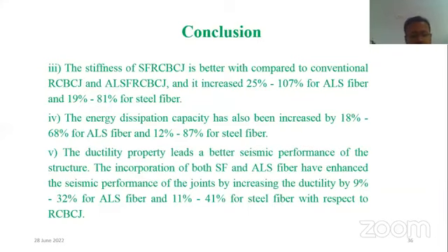In terms of energy dissipation capacity also we can compare, and the energy dissipation capacity increased by 18 to 68% for ALS fiber and 12 to 87% for steel fiber.